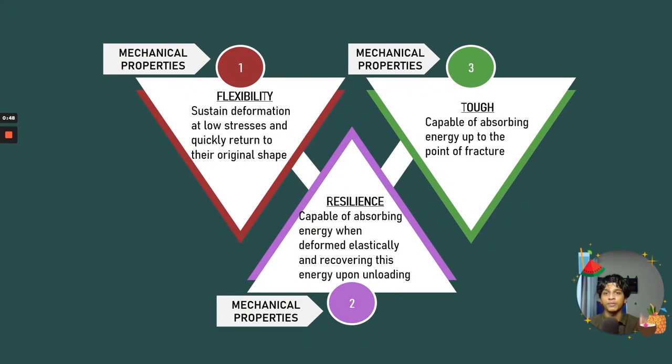For the mechanical properties, it has flexibility, where it is able to sustain deformation at low stresses and quickly return to its original shape. It has to be tough, where it is able to absorb energy up to the point of fracture. It also has to be resilient, where it is able to absorb energy when deformed elastically and recover this energy upon unloading.